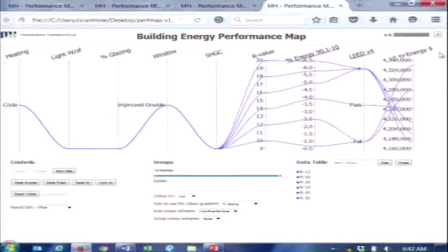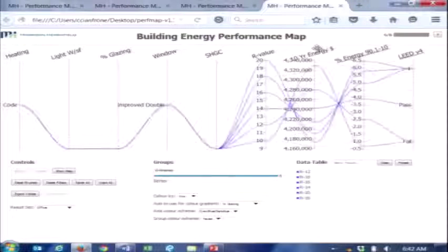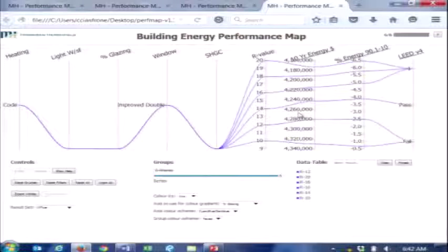And the energy, well, let's look at energy cost. So the energy cost you can see between R10 and R12 is about $50,000 over 10 years. And so you would weigh that against the capital cost to do that. So if my objective is to have a 10-year payback or less, and the decision was to improve my R value from 10 to 12, you'd say, okay, well, is that cost effective? There's a $50,000 savings annually. Is that something that makes sense?